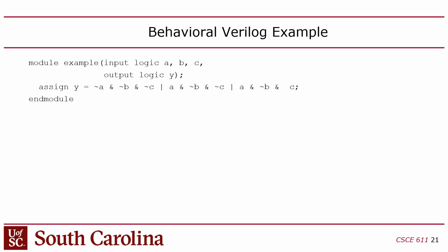Now, in reality, when you put this in hardware, there is a delay between changing one of those inputs, A, B, or C, and the corresponding change of Y, right? There's a logic delay in there. You guys know where a logic delay comes from? What causes that delay? What causes that delay is capacitance and resistance, right? So when you change one of those inputs, you're actually charging or discharging a capacitor in that logic circuit. And so there's a little bit of a delay before the change of input propagates to the output. However,